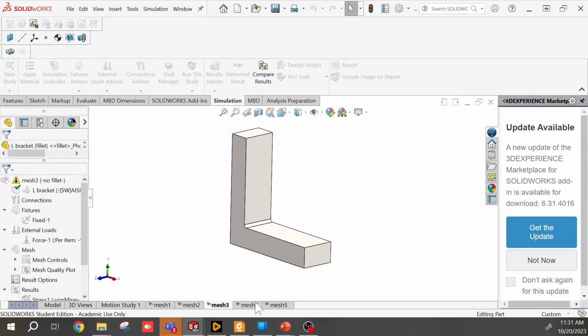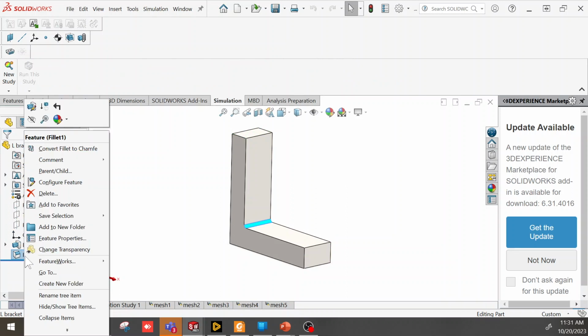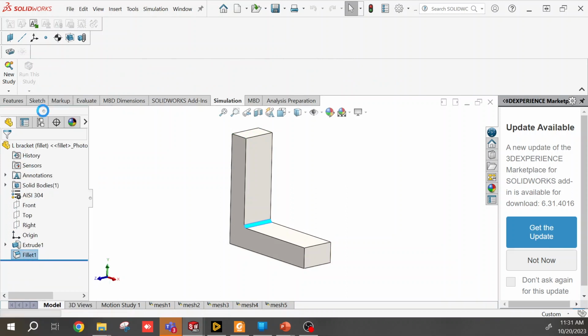But what I'm going to do here is delete this fillet first, and we're just going to mesh it ourselves. So I encourage you to use mesh 4 here because this is the one that's set up. I will go back to the model and right click on this and suppress it. So it's going to turn this into a sharp corner.